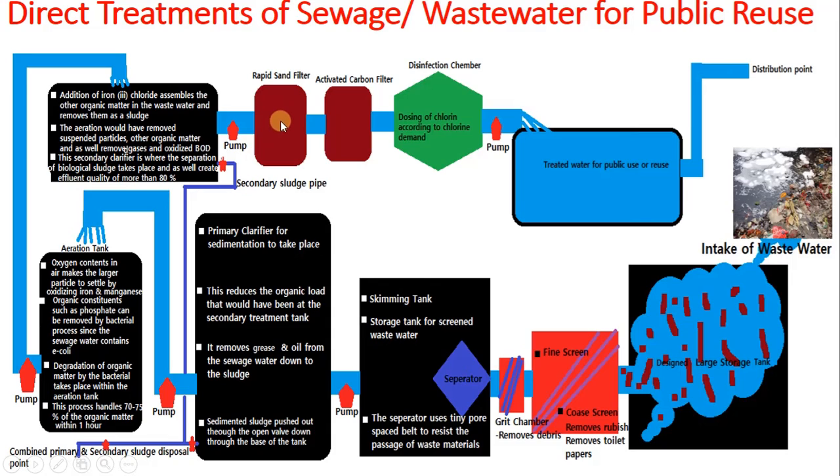After the removal of turbidity, the water will flow into the activated carbon filter. From this activated carbon filter, it will handle micropollutants, which none of these handled. After handling micropollutants, it will as well remove residual iron trichloride and it will remove color, taste, and odor.